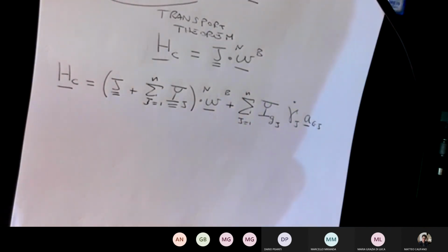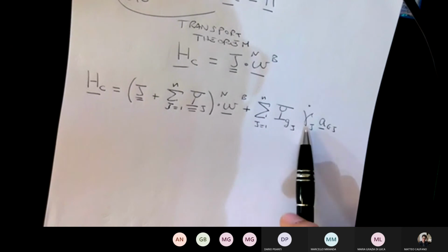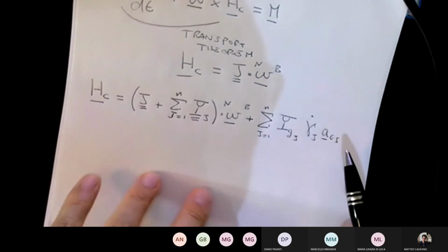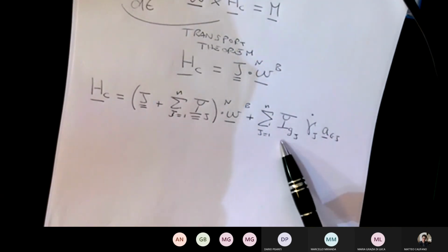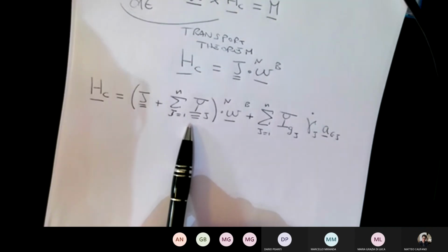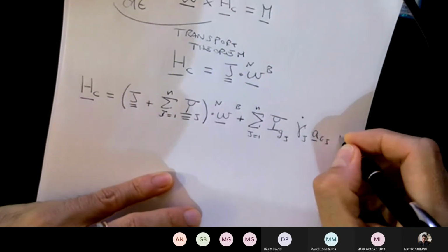This is the contribution to the angular momentum due to the fact that the gimbal can move. Okay, and so it's a contribution along the g axis. Basically what I'm doing is writing something like this, specialized just to that particular motion. So you have the moment of inertia, not the matrix, it's just a moment now about that particular axis. Again, keep in mind that these J and these Y matrices are in the respective principal axis, so the matrices are diagonal.